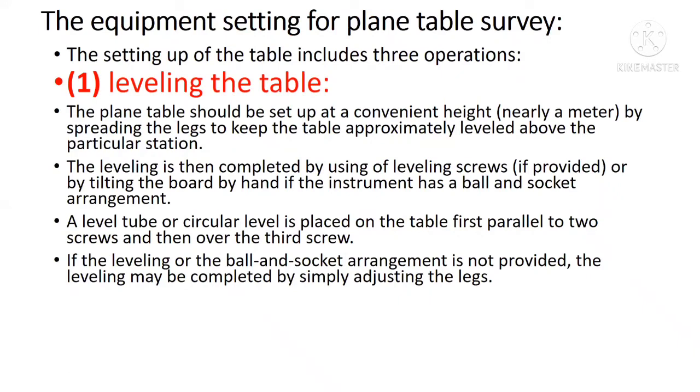Now the second is the equipment setting for the plain table survey. There is a set format to place the plain table and to adjust it. Okay, so there are three steps you have to basically follow. The first one, which is very important, is leveling the table.